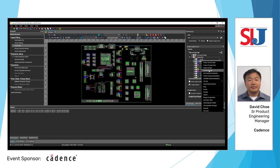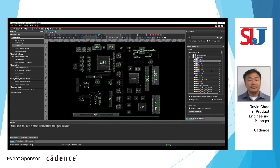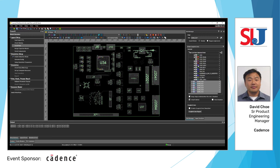And in this case, I'm going to disable all of the nets. Make this a little bit bigger. And we're going to do a quick search for DDR0 DQ star and hit the enter key. This selects all of those nets that start with that, with a wildcard, and I will enable the selected nets. So now we have all of the signal nets, which are accounted for.